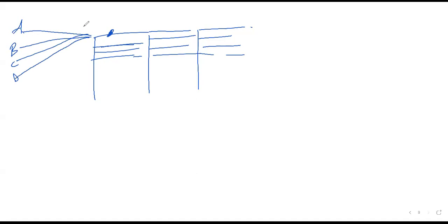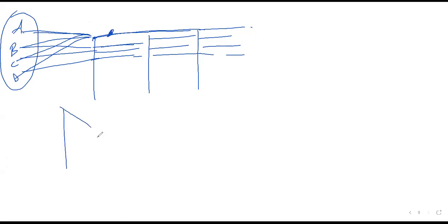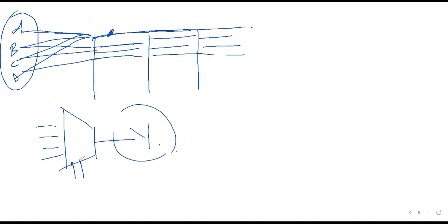This transmission line transmits the information of all these people at the same time. How does it do that? Without the multiplexer, I would have to make use of all 4 lines here. A uses this one, B uses this one, C this one, D this one. With the use of the multiplexer though, all of them are summed to one output.